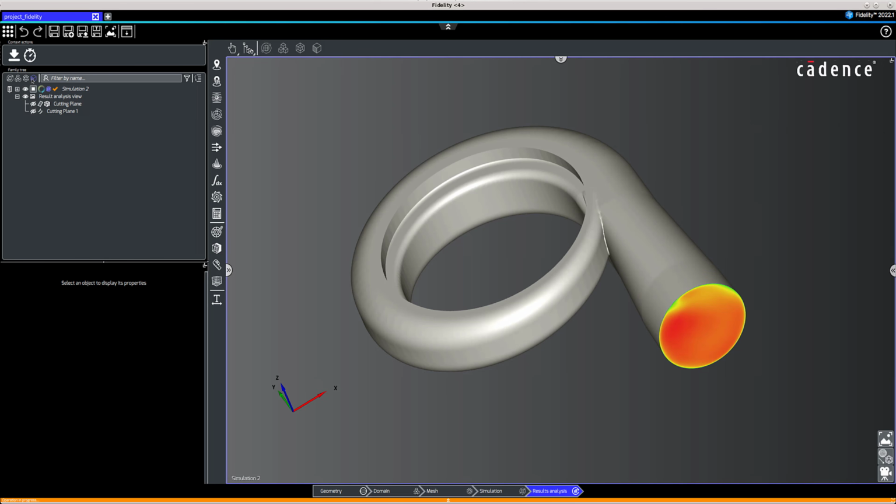Now let's talk about filtering the tree by name and by category. You can filter by name based on the following search patterns: contains a pattern, start with a pattern, end with a pattern, or using a regular expression, such as the asterisk wildcard. The search input fields can be cleaned by deleting the search patterns or clicking on the cross icon to the right.